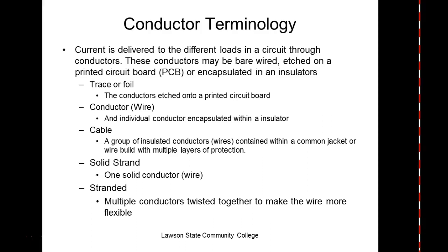Usually stranded, the gauge is slightly bigger, but not much. The ampacity for stranded is a little bit higher than for solid, but it's nothing that we need to understand. So what would be the advantage of stranded over solid? Flexible, that's it. It's flexible. Solid is easier to terminate and splice.